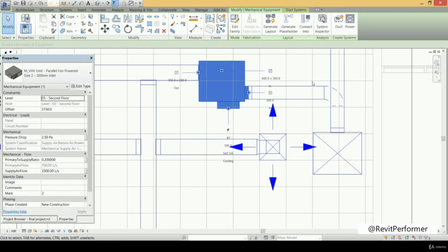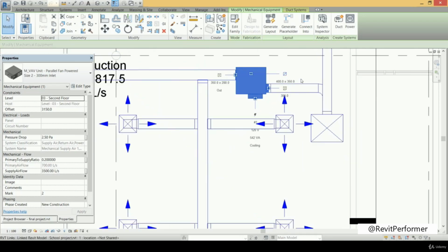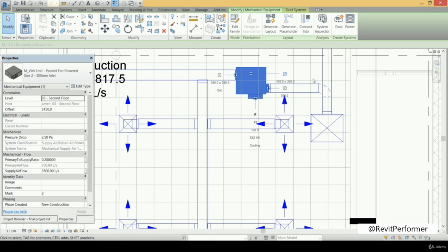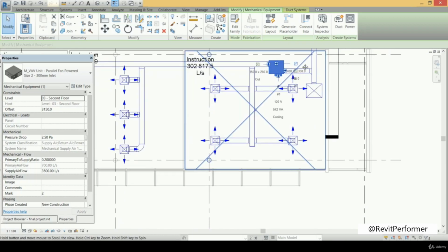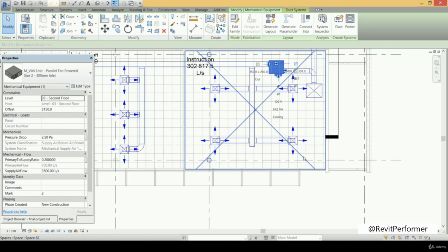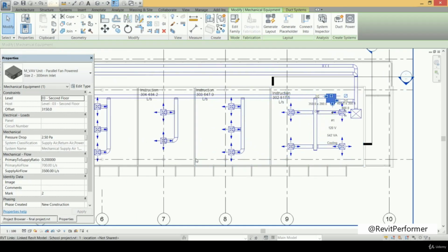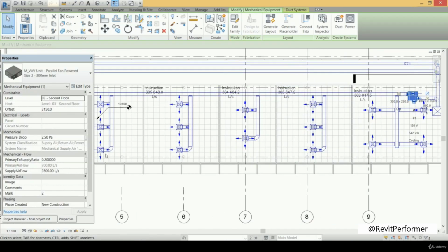And for that purpose, we need to make the usual trick, which is to increase or decrease the offset of the return duct. So if we change the offset of the return duct generally, we will have no problem as it will not interfere anyway with the supplying duct. And the plan that we have now for routing the return duct is to go out of the VAV box with a duct in that direction, then we go in that direction here, and then we go forward in that direction to feed all the spaces that we have.